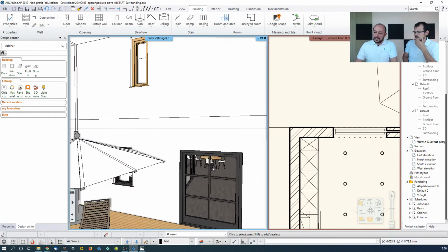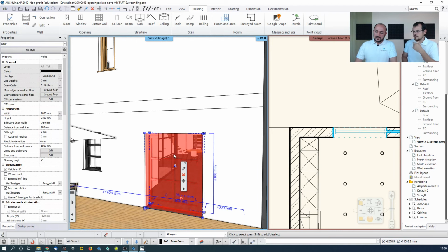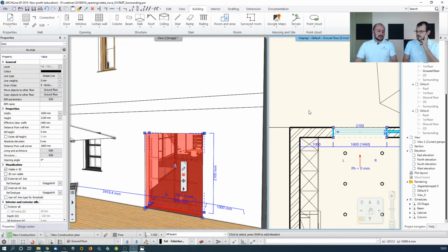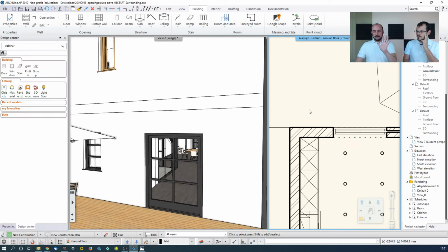Yes. So to be able to place it there, I need to know the size of this object, which is 2100. That's the height. And perhaps I will just use the half, which is 800 for the width for the shutter. But it's actually just something that you can customize later on. Again, this is a command that you can start either from the 2D or in the 3D. Now I started from the 2D.